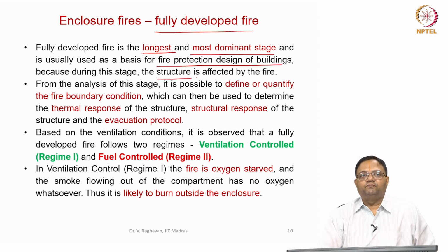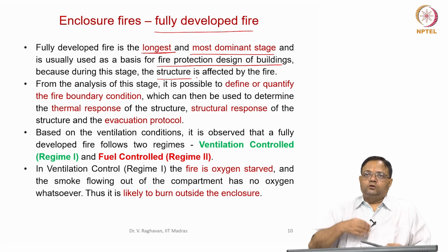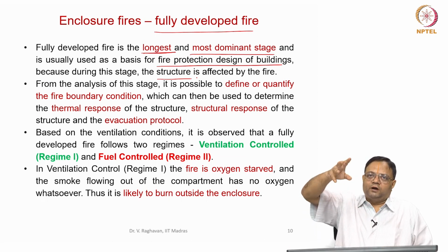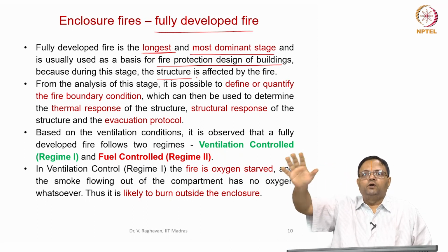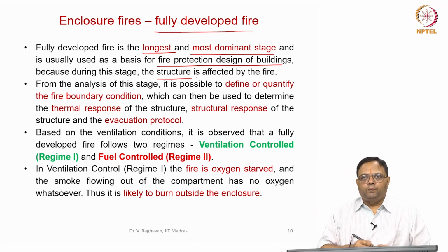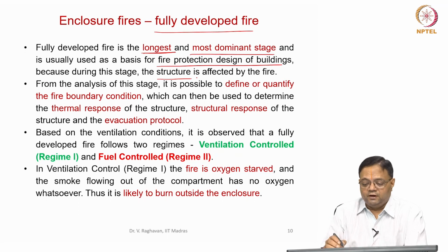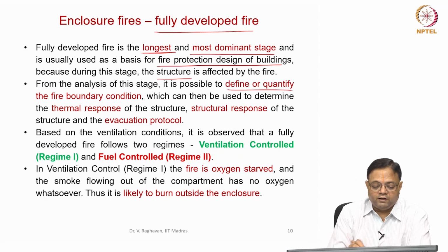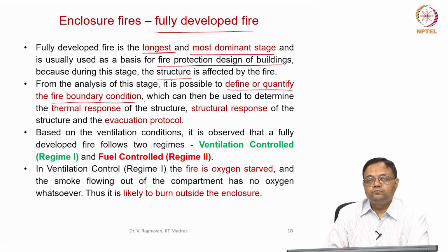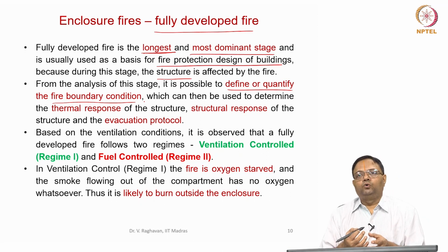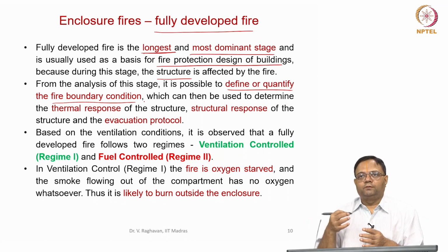That is, the structure can fail now. Okay, so this growth stage, flashover conditions and the fully developed stage have to be analyzed properly. In this stage, basically we can define or quantify the fire boundary condition, whether the fire will lead to propagation from one room to other.